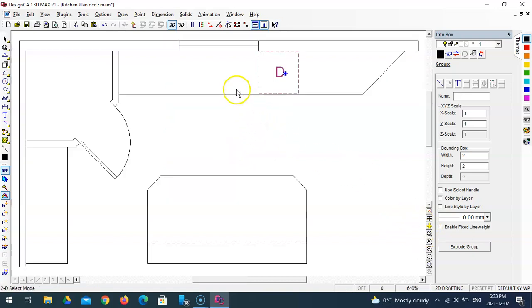Now, the dishwasher is placed beside the sink. And the reason we do that is because we steal the plumbing, basically, for the dishwasher. The drain plumbs into the sink drain, and we also get our water, which tees off from our sink. So that's why the proximity to the sink. Also, it's just better design. We can rinse off our dishes and then just put them directly into the dishwasher without dripping across the floor. Another possible location would be on the island. However, you're still going to be a little bit farther away, and then you can't use the plumbing that we have already in place from the sink.